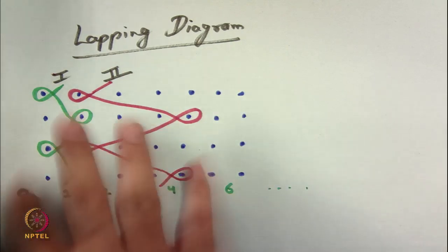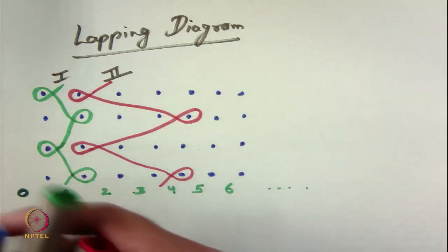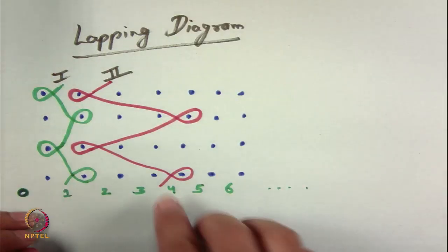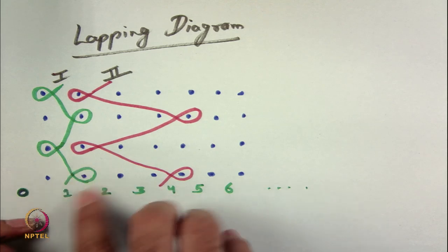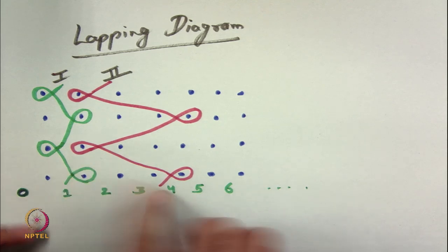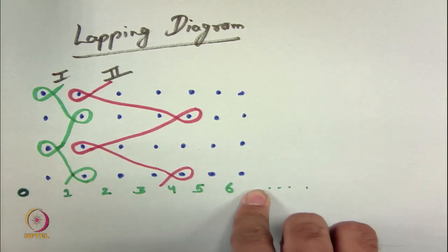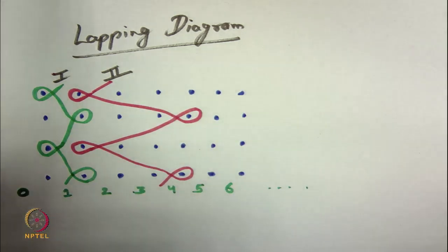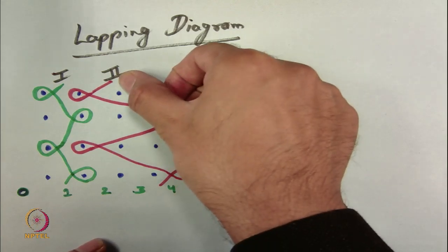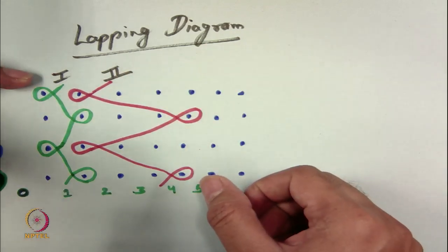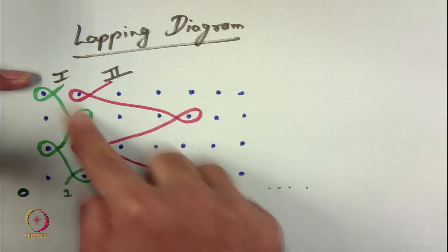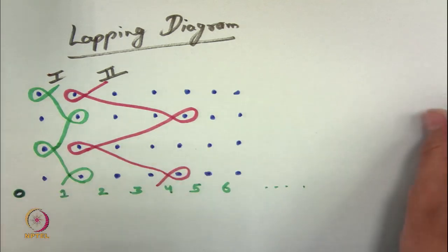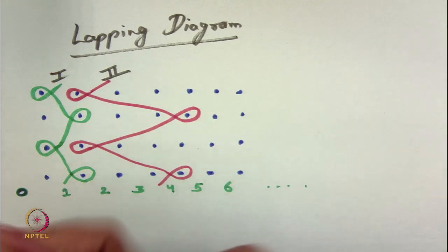Now, we can simply represent this diagram with some numbers. Okay. So, you need not get confused that we need to start only from the first position or fourth position. You can start from any position of the guide, and the only difference is that the underlap has to be 3 units for the second guide bar, and for the first guide bar the underlap should be 1 pitch. This is what you only need to think about, otherwise every other thing is normal.